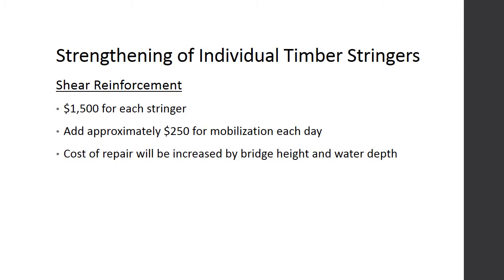For the strengthening of individual timber stringers where additional shear reinforcement is required, the cost is estimated to be $1,500 for each stringer repaired. The cost of mobilization, estimated at approximately $250 per day, is in addition to that estimate. One should also note that the cost of repair may increase depending on the bridge height and water depth dictating the equipment required.